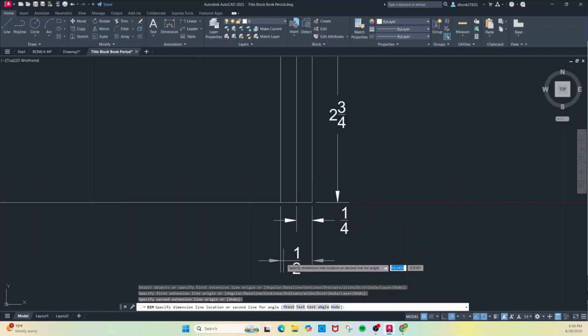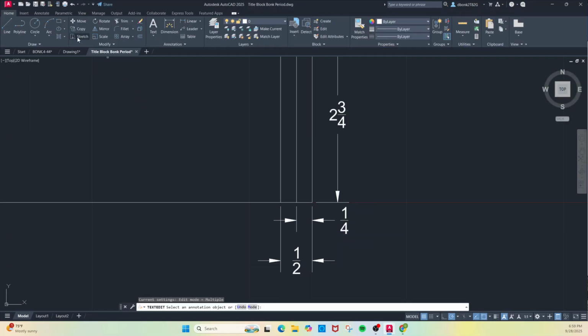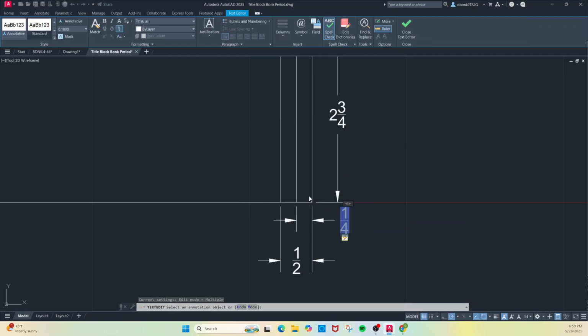Since these don't quite fit so well, when you place measurements, you can toy around with them a little bit, and you can double click it and you can change the measurement over here, and you can reduce it to something smaller until you can maybe get it to fit. So you just double click it, get this command, type in 0.4, let's call it.